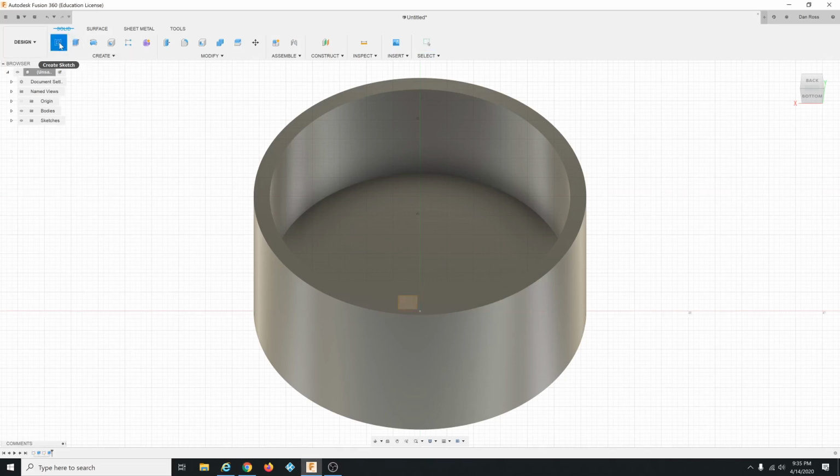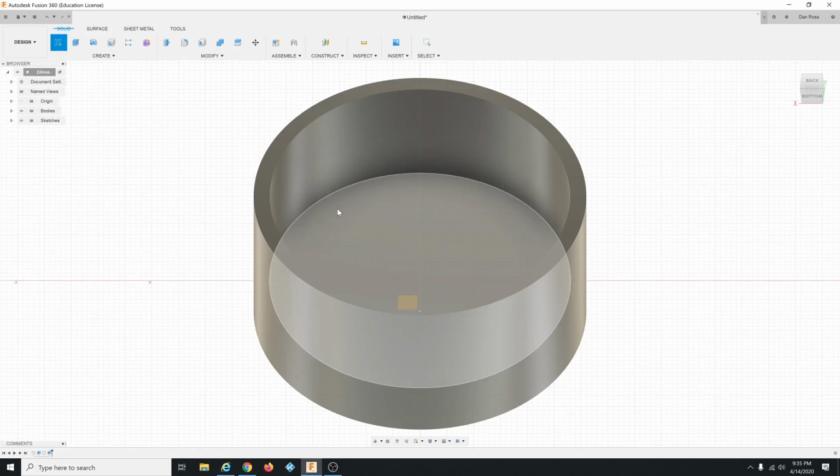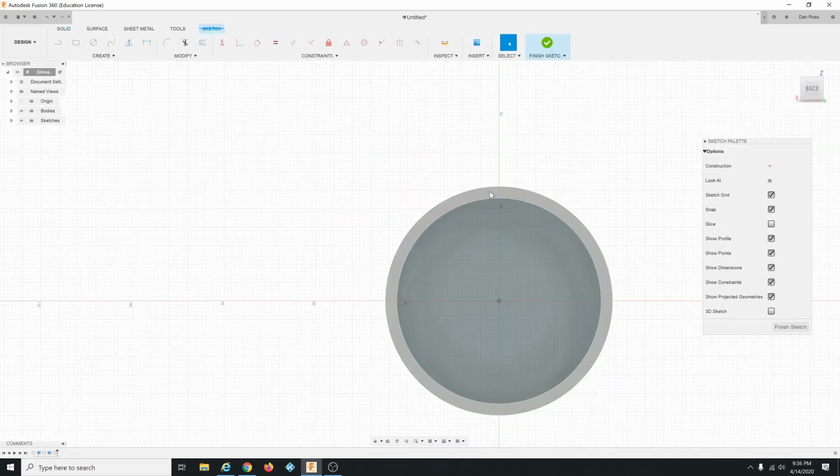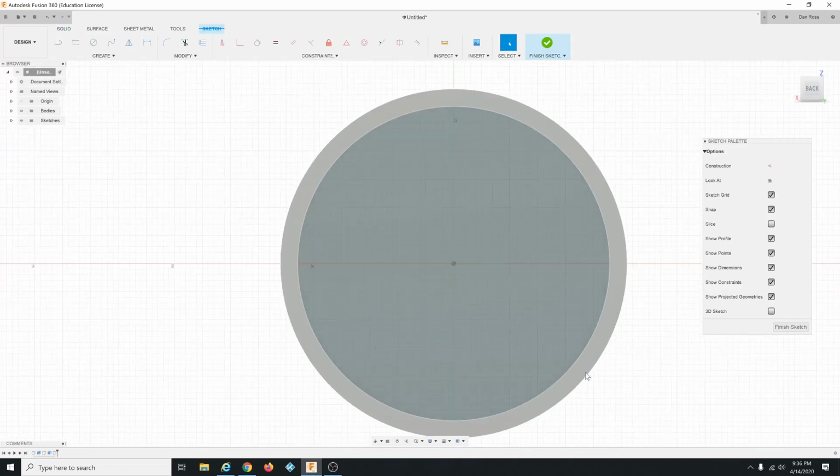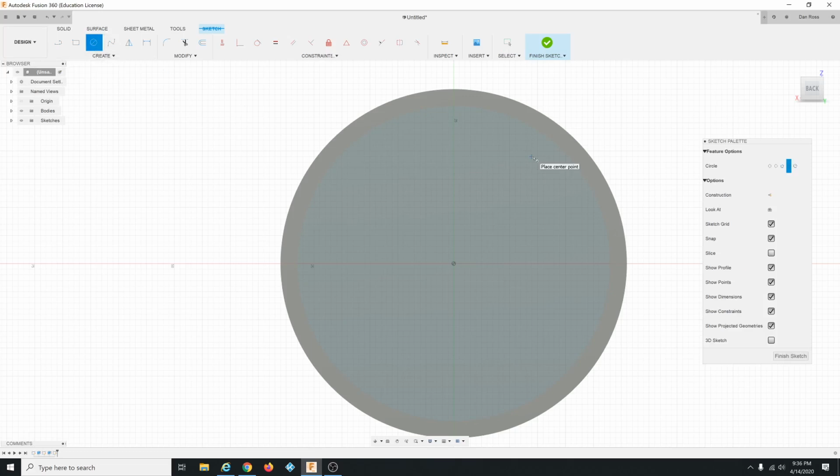Start a sketch by clicking this create sketch button, then click the planar face. In this case, it's a planar surface on the object. They call that a planar face. Click that. I'm going to scroll with my zoom to get it centered. Okay, then do a center diameter circle. Click that button. Put it just kind of there. Doesn't matter exactly where. 4 is the diameter. Enter.